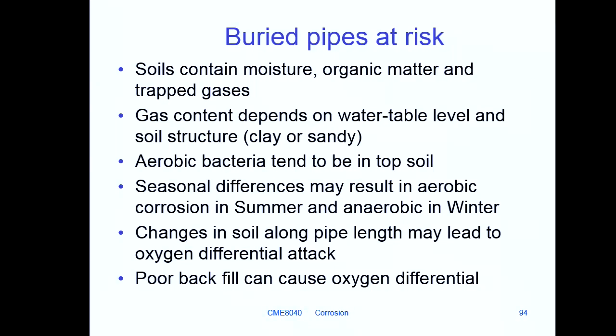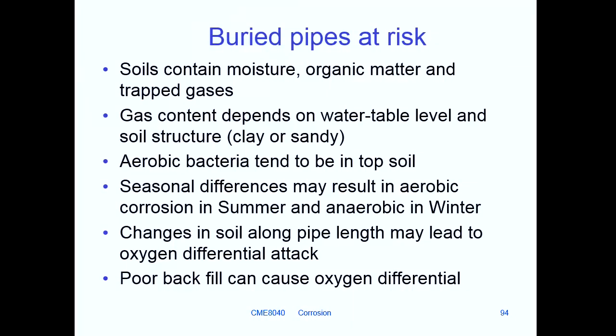And then the other one is the backfill situation, where you've got lumps of clay that have just been randomly dumped back in the hole, and some of them are in contact with the pipe, and that gives you again an oxygen differential situation and enhanced attack. And there are all sorts of statistics about corrosion, but the estimate, at least in the UK, is that half of the corrosion problems of buried pipes are associated with MIC, associated with bacteria.